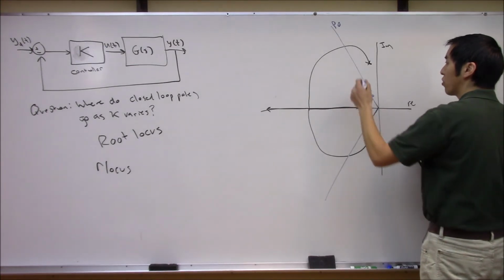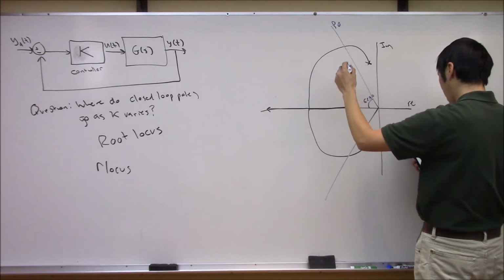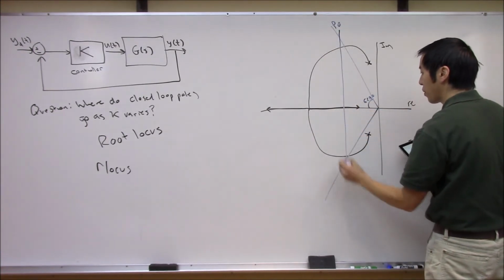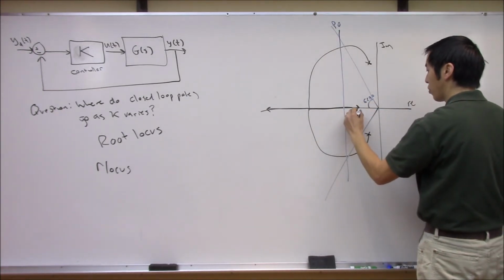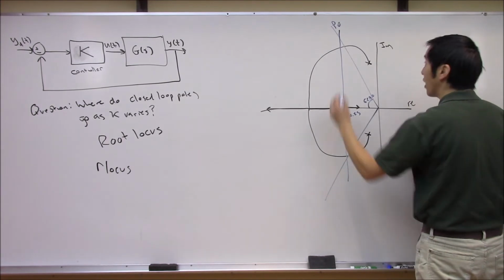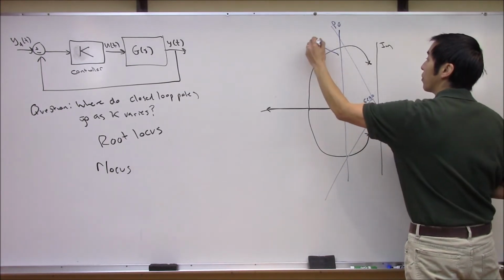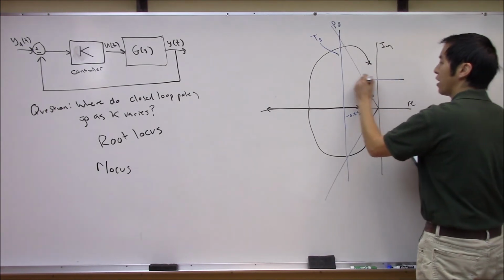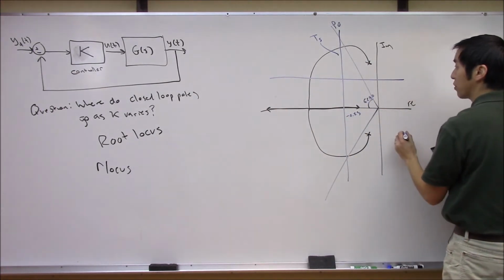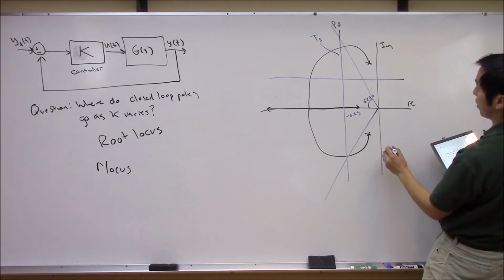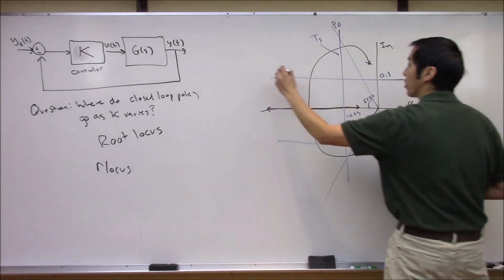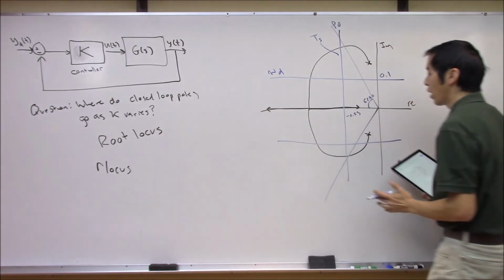There was also another restriction on sigma, which I think was at minus 0.23. This was our settling time restriction. And finally, we had the damped natural frequency, which had better be something like this, at 0.1. So here was our omega D requirement.